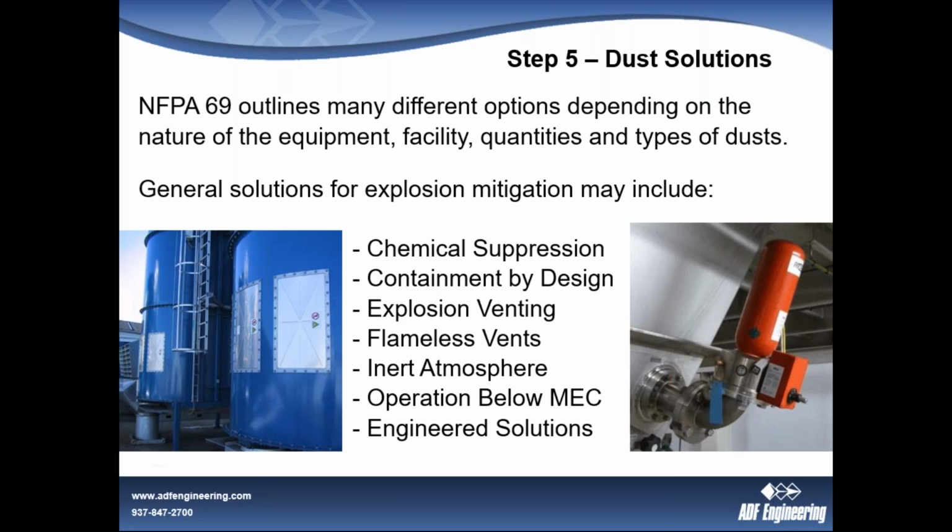Are flameless vents an option when you have a dust collector that's indoors? Yes, it can be. Those are the kind of things you need to evaluate. Inert atmospheres, if it's an external outside tank, that's great. If it's internal, that creates its own problems. So you need to deal with that as well.